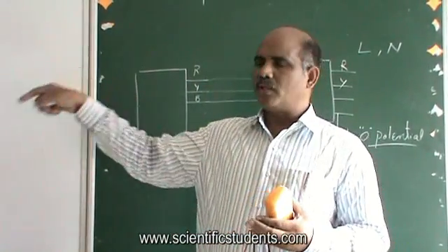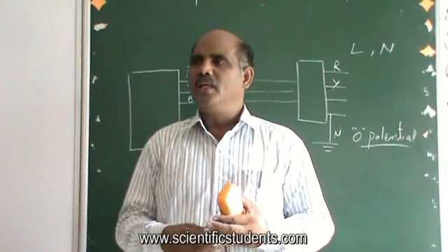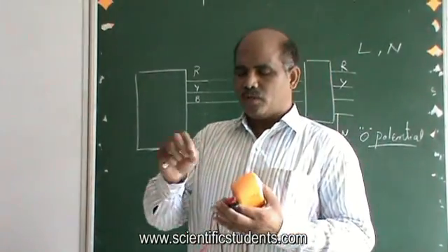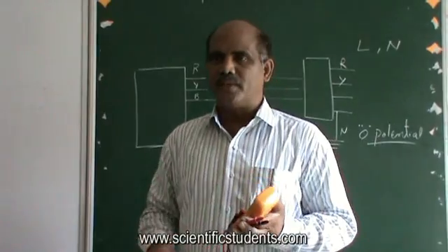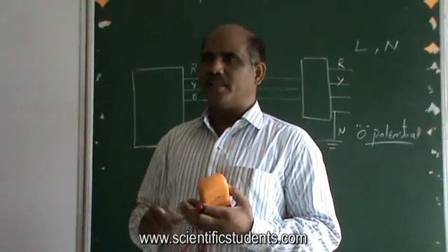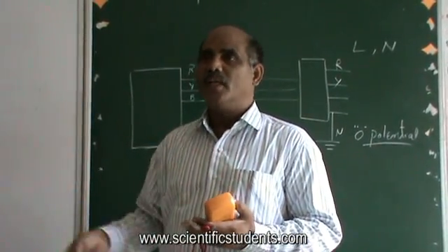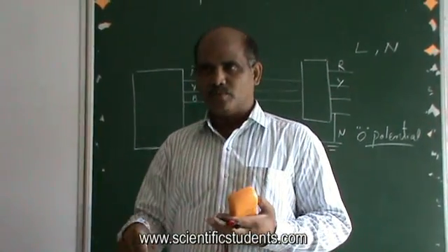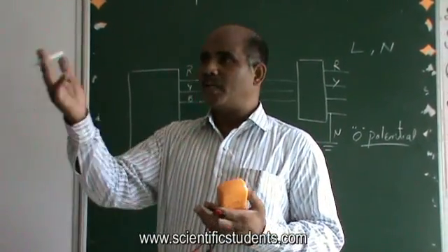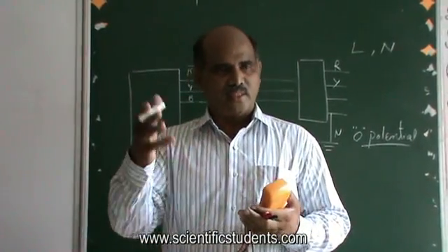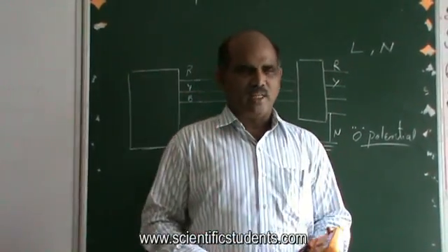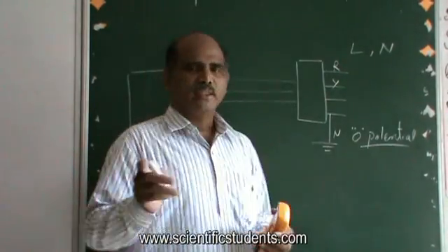So at a particular ground level where three phases have come, we can check neutral to all the phases, see what the voltage is, and note down that R phase is this volt, Y phase is this volt. Then whenever you go to any classroom and check, if you find 230, that means R phase, because you already noted it, so you understand this room is connected to R phase. If in the main meter area Y phase is 220, and you find phase voltage 220 in a room, then you can tell this room is connected to the yellow phase wire. Likewise, you can have a thorough understanding of the three phase system.